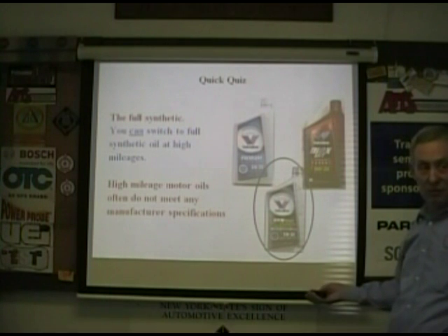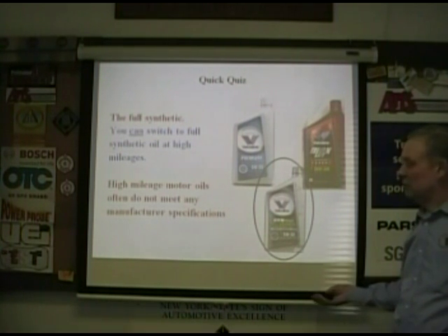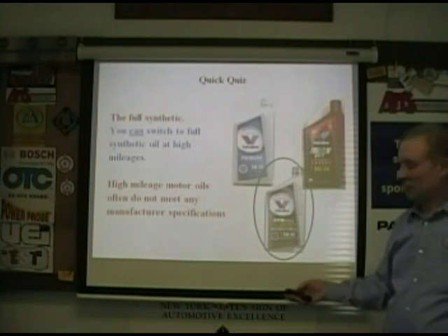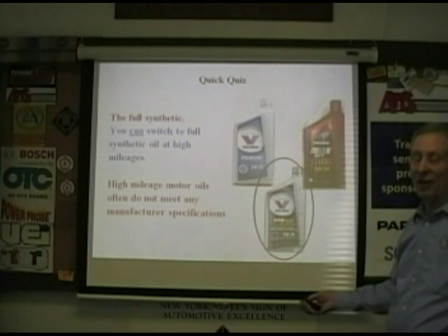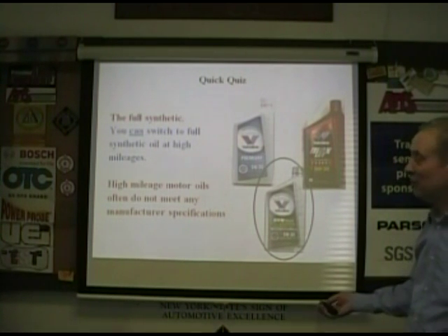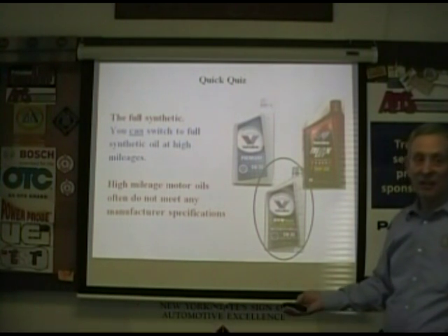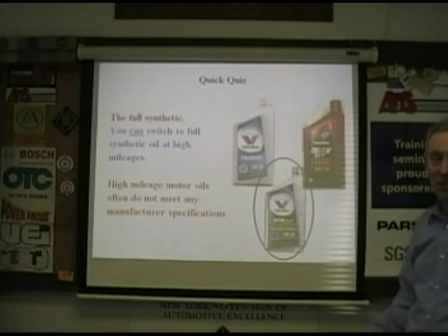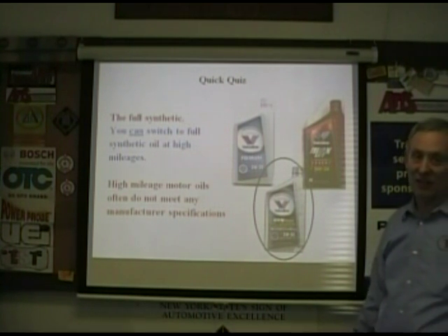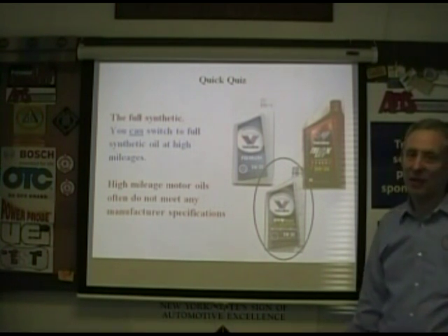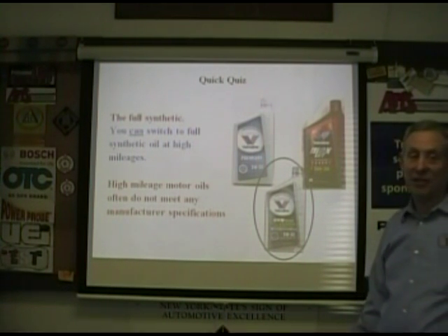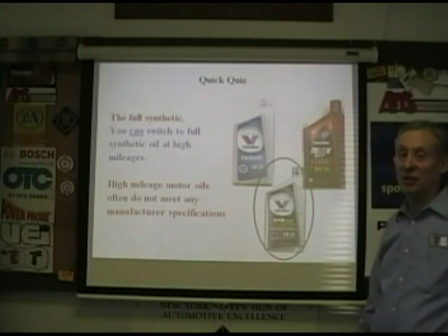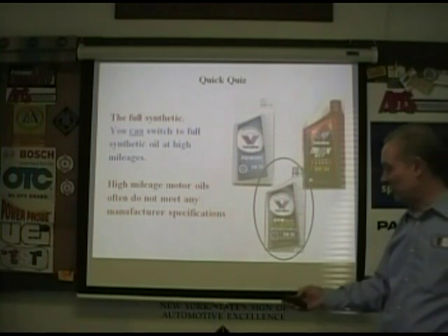Is it true that you cannot change from synthetic to regular, or vice versa? That's actually a bit of a fallacy, but there are some risks involved. It used to be that if you switched from regular petroleum oil to synthetic, on a high mileage engine, there was some conditioning of seals going on and they would leak like sieves. I don't think that's true anymore. But you do have to watch going back and forth. Again, read the specs. I would recommend not doing that. You'd probably have to flush it out with a...